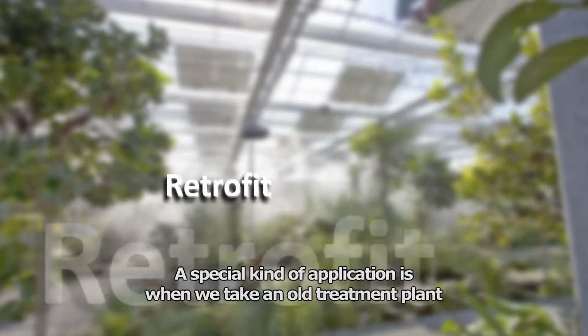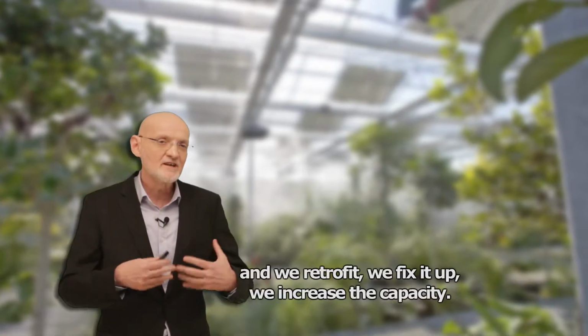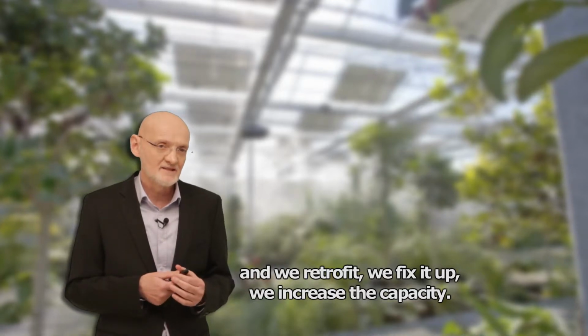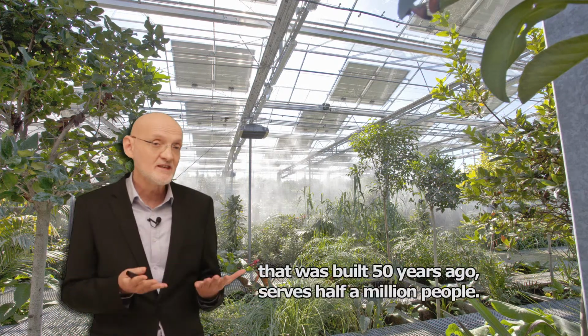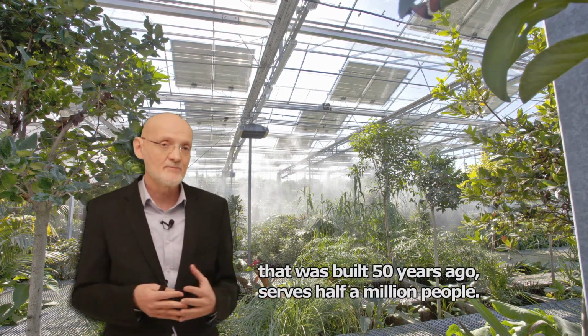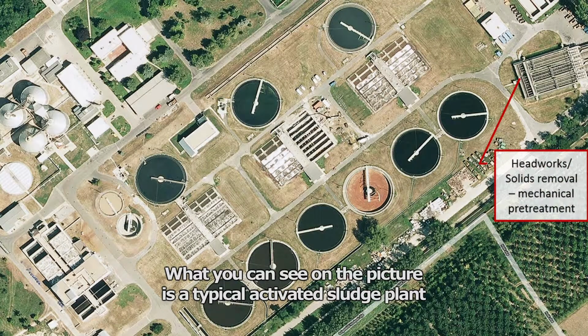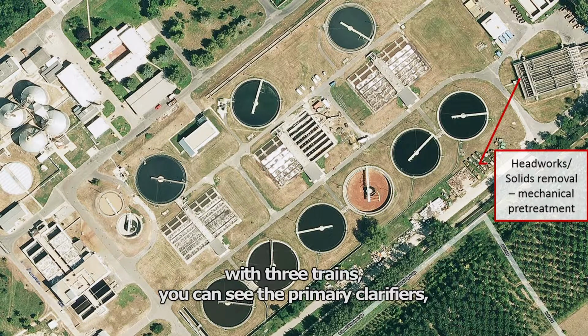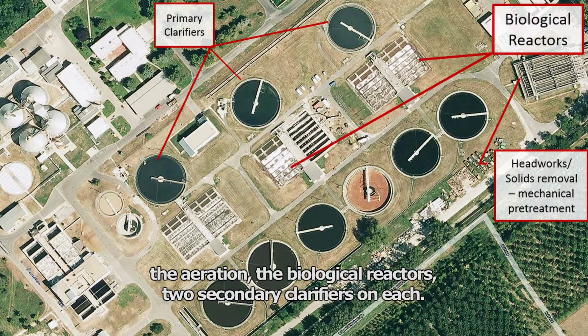A special kind of application is when we take an old treatment plant and retrofit it, we fix it up, we increase the capacity. The example I'm going to show you is a treatment plant that was built 50 years ago, serves 500,000 people. It's about 80,000 cubic meters in capacity. What you can see on the picture is a typical activated sludge plant with 3 trains. You can see the primary clarifiers, the aeration, the biological reactors, 2 secondary clarifiers on each.